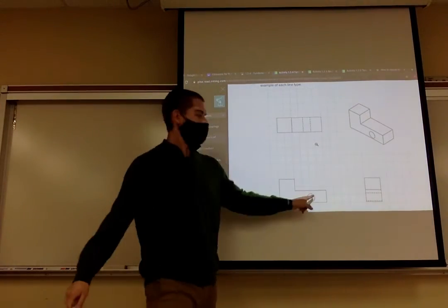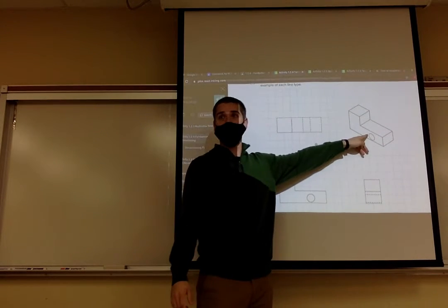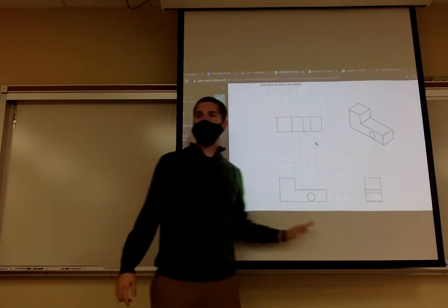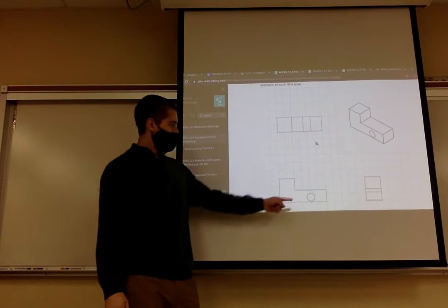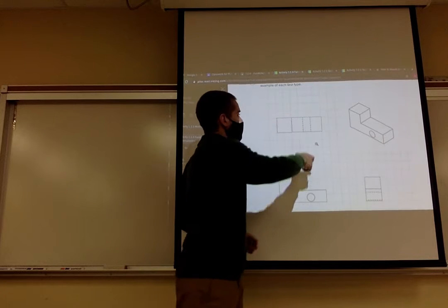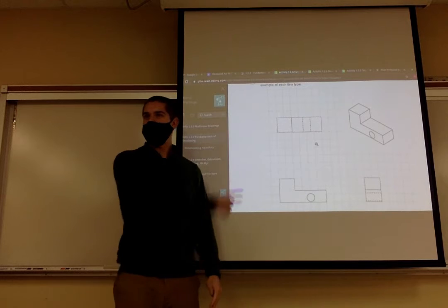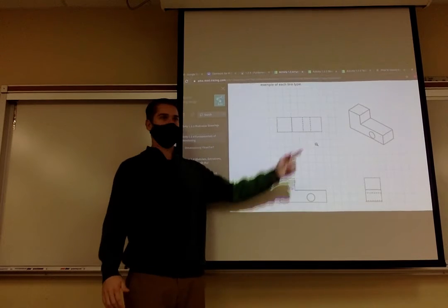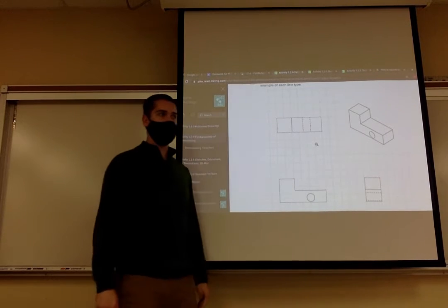They're both orthographic, but I want to show you an example. I have this hole. This is my front view, my right view, my top view, and the isometric. This is standard. You should always get used to doing it: front view, right, top, ISO. My hole is here. I see where the hole is going from the top. It's coming through the middle of my object. And I can also see it on the right view. Well, where do I dimension the hole? It's in all three views. Where do I actually put the dimension and say this hole is 1 inch in diameter?